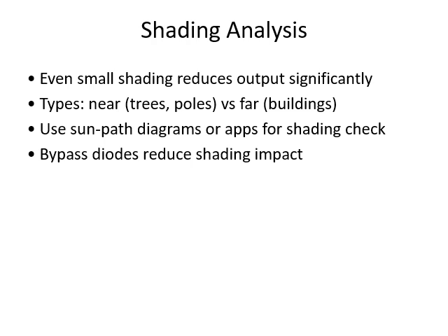So we should also be tracking the sun path diagrams, and the bypass diode is an important element here. This bypass diode is a small diode. It is connected in parallel with a group of solar cells, right? So maybe one bypass diode covers up to 18 to 24 solar cells.